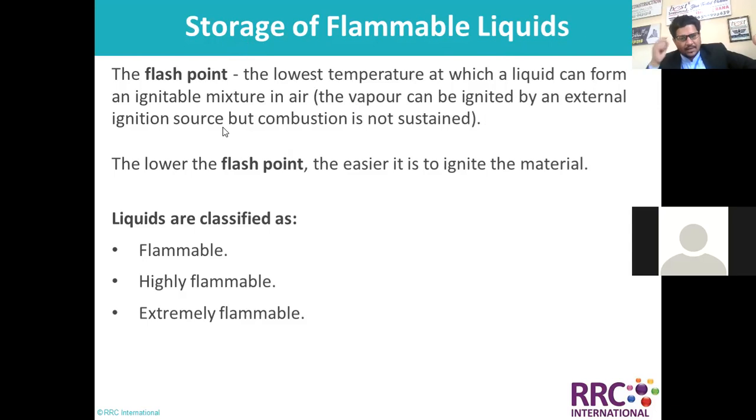When I am buying any chemical or any sort of liquid, I should check the flash point. And I can find this flash point maybe from the TDS technical data sheet, maybe from the SDS safety data sheet, in other words the MSDS, or in Aramco maybe the chemical hazard bulletin.